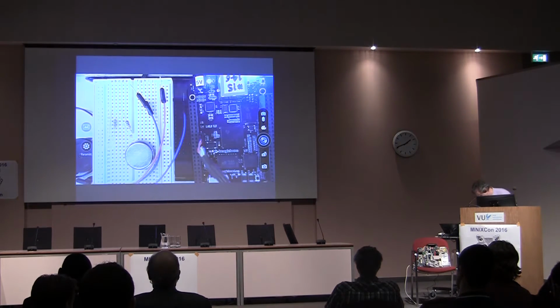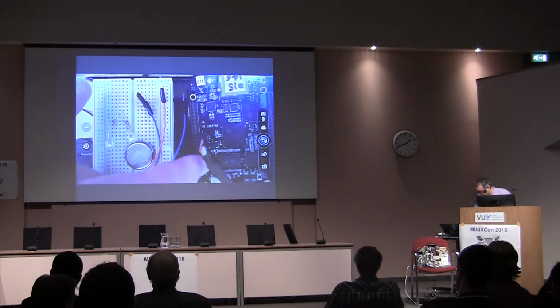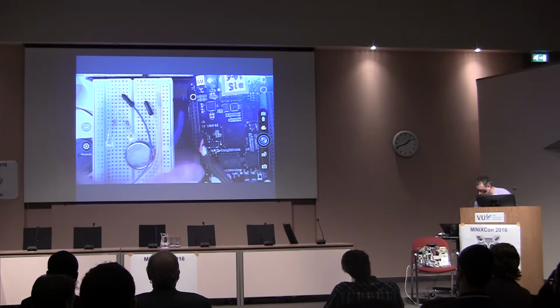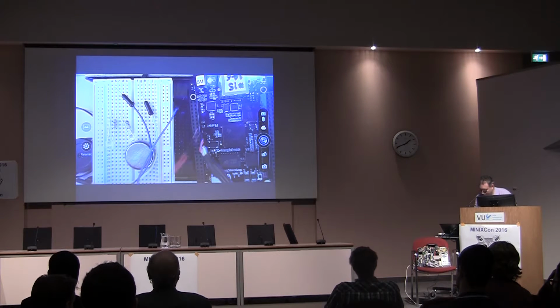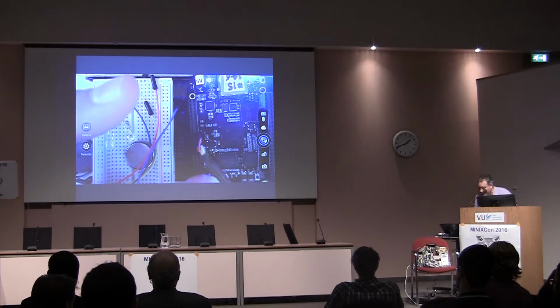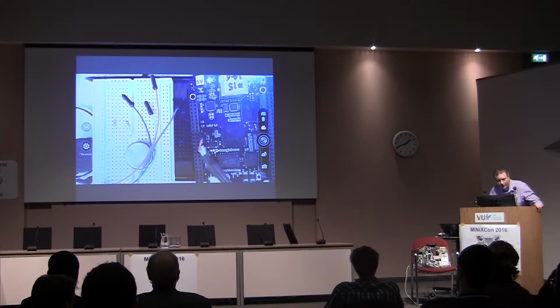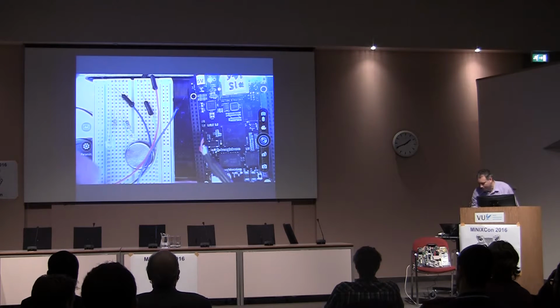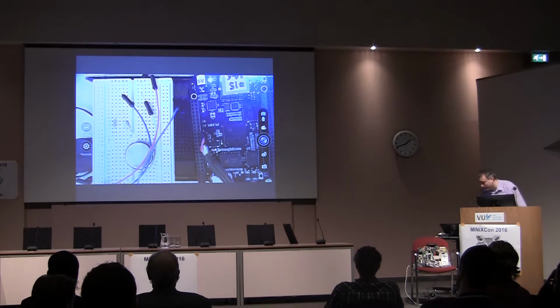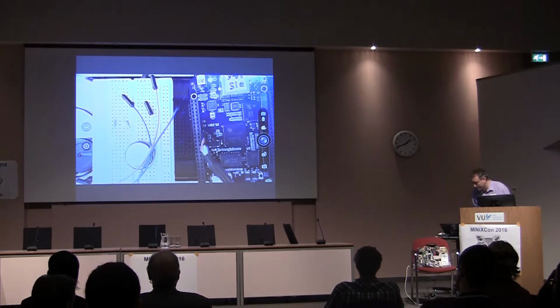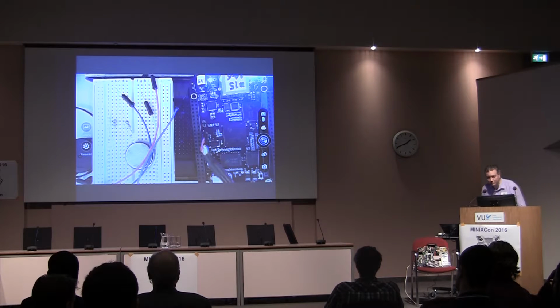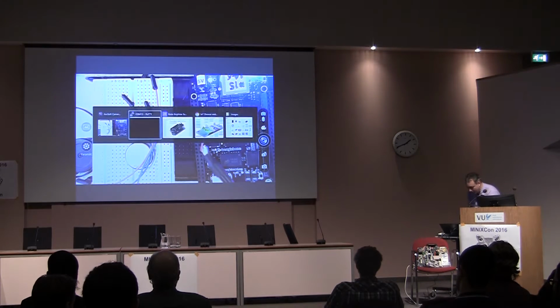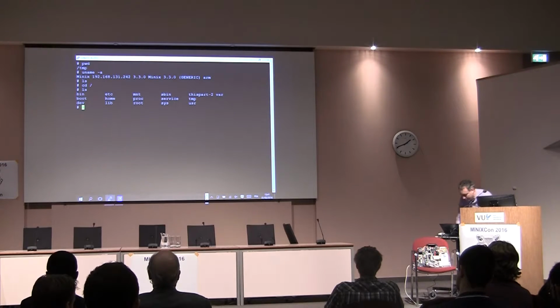I'll show you what the GPIO looks like physically. You see this row of plastic? Arduinos have this as well, for example. The Arduinos have male pins, so you see the copper, or the brass, or whatever it is, copper, I think. And here they have the female headers. Yes, there are connections either way, but those are the GPIO pins. Not every single one of them is GPIO. Some are UARTs and others are power or ground. But that's basically what we're going to manipulate now, and let's do that.